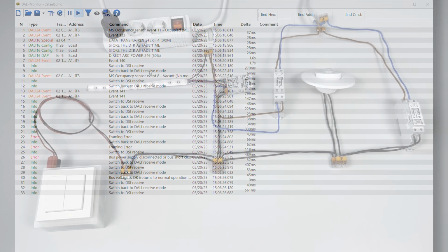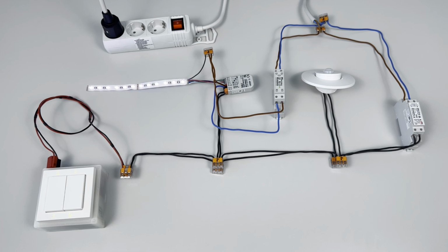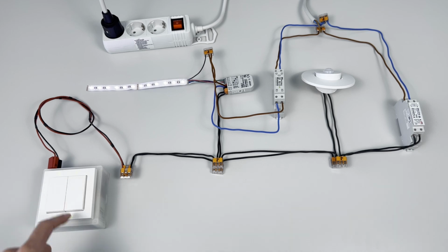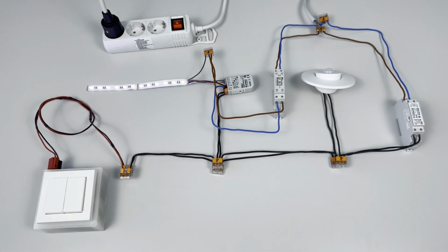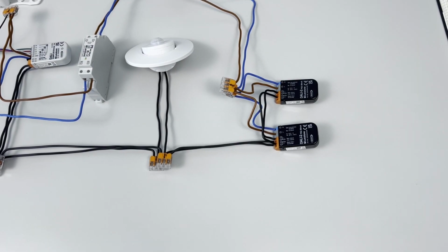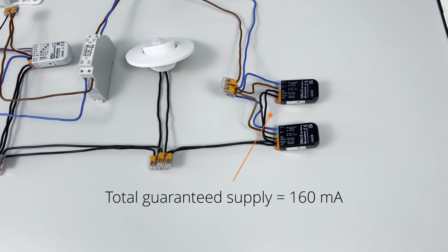Lunatone devices will stop communicating if the bus voltage is out of specification. This is to protect themselves. However, note that voltage levels close to 16 volts, which is the normal DALI voltage, may not be detected as problematic until damage occurs. Additionally, if you discover devices with a damaged DALI circuit, always check the bus power supply as a potential root cause for the damage.